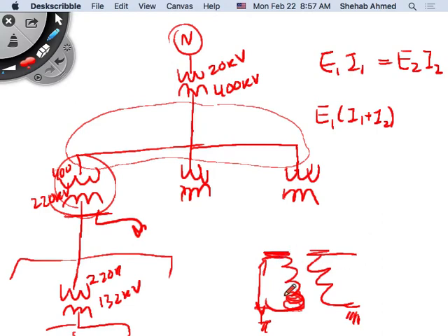In an autotransformer, on the regular transformer, I have low voltage, so low insulation here and low insulation here. But now if I use this as an autotransformer, I'm taking this point and connecting it up here, right? So that means insulation levels down here can no longer be the lower levels. I have to use thicker insulation because I'm already at a high voltage up here with respect to my ground, right? So from an insulation perspective, autotransformers may be a little bit more expensive, but forget about insulation. You would use it mainly because of this characteristic: the ability to transmit more power, transform more power.